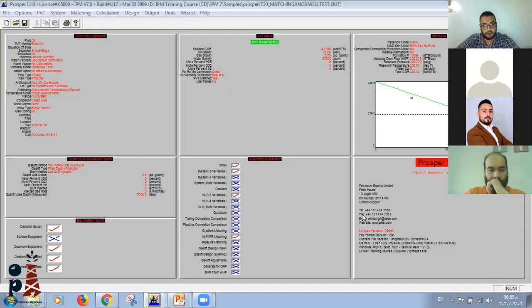Then I put in the data of the IPR, and then I have new test data. I will make a calibration of the model. I will calibrate, for example, the flow correlation that is used to calculate the pressure drop along the wellbore. So for sure we are using it, and maybe if we have another session, we can go back into details to show how this happens, how you start from a theoretical way with the data you have, and then calibrate it to the actual data.